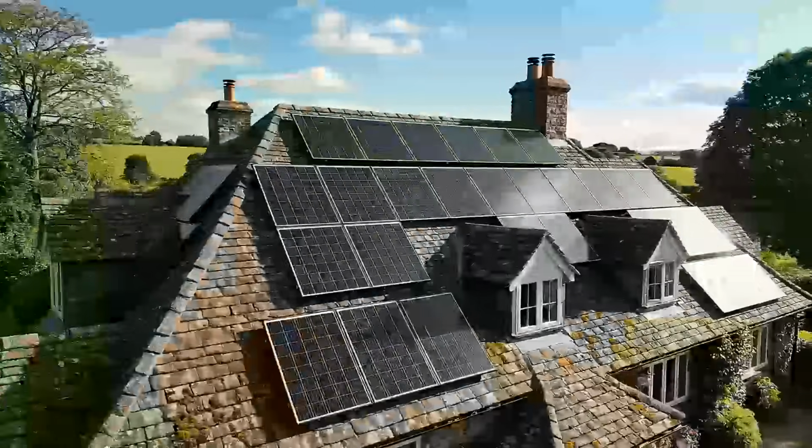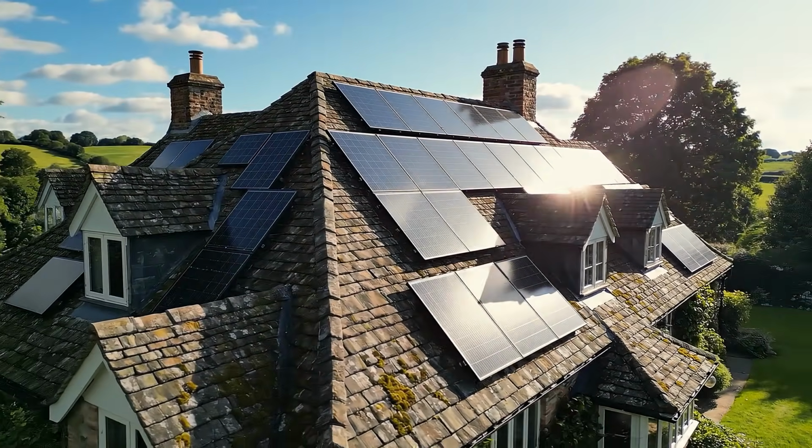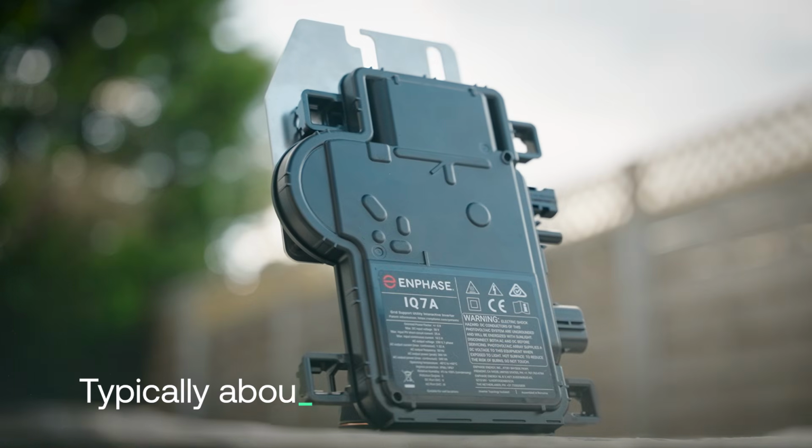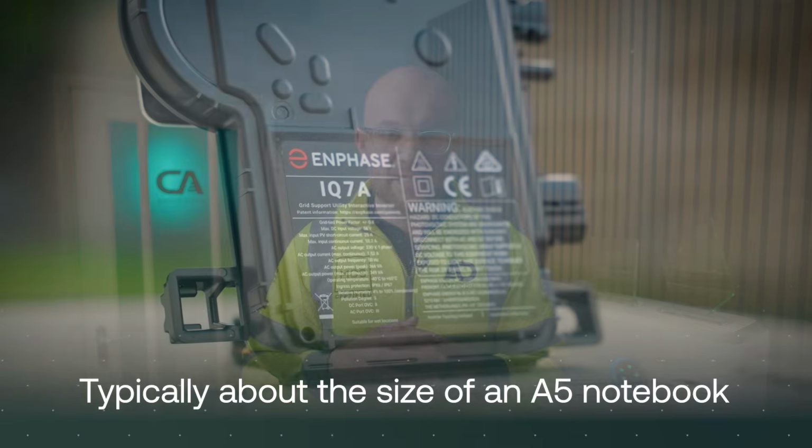The main reason for microinverters is higgledy-piggledy roofs, because we need a minimum number of solar panels to go on an inverter for it to work. So by having a microinverter, by it being really small, we can get away with fewer solar panels. These are great for awkward roofs. These are also great for individual panel level control.